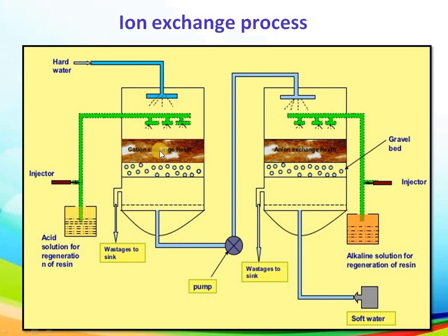Okay, and this cation exchanger bed retains the calcium and magnesium salts present in the water. The H plus ion and the rest of the negative salts like chloride, sulfate and bicarbonate are passed through and enter the anion exchanger resins, where all the chlorides and sulfates, these types of minerals, are trapped by the anion exchanger bed.